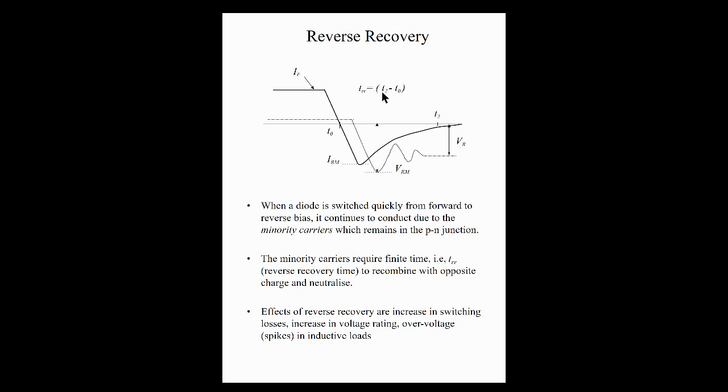Now, how do we define our reverse recovery in this case, right? It's just the time that it takes for the current to go towards 0. The current switches from the on state where it's high, and then it settles at this point.